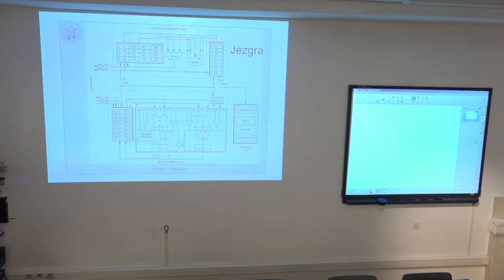For example, stack pointer and frame pointer are used to implement the stack or to implement the frame in some higher-level language implementation in C. So these two are dedicated, while the remaining registers, P1 to P5, are general purpose address registers, which can also be used as a source of effective address. But as is shown here, they are used only with data address generator 0. They cannot be used as an argument for DAG1, only for DAG0.